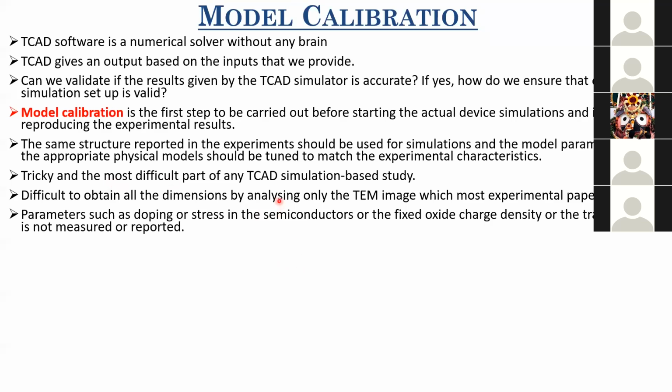Second, when you are fabricating the devices, the doping cannot be uniform, because the process is inherently ion implantation. So your doping has to be non-uniform. We just know the doping dose. In the experimental papers, you'll know about the doping dose and the dopant energy with which these dopants have been bombarded onto your substrate. From there you have to calculate the doping, and this doping is not uniform in the device.